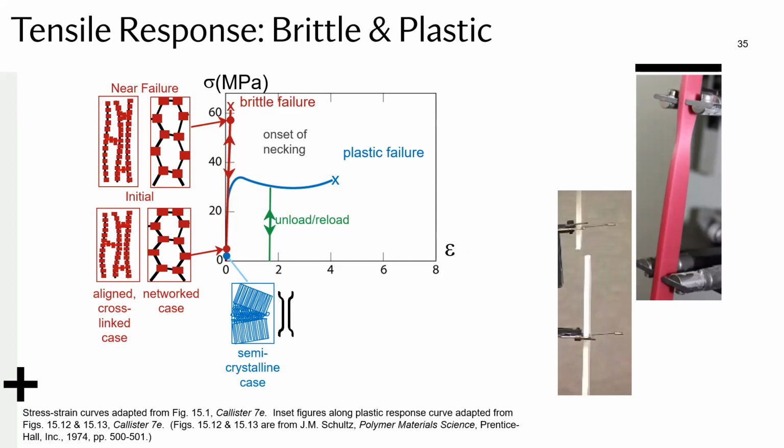These amorphous regions that are sandwiched or mixed in between the crystalline regions are going to get stretched. As you continue exerting higher stress levels, you can see that it stretches out those amorphous regions, and they're just going to elongate and get more and more aligned.